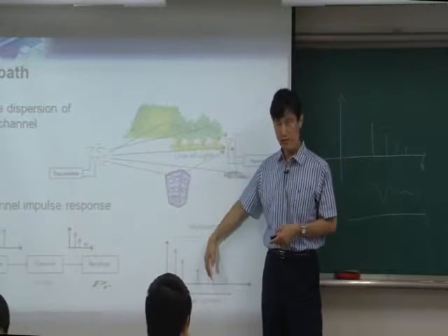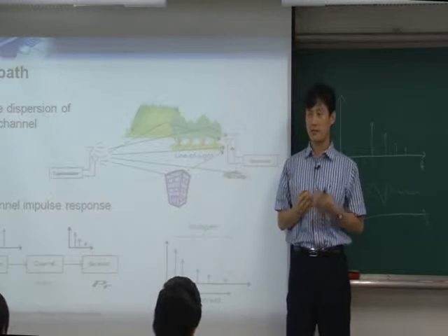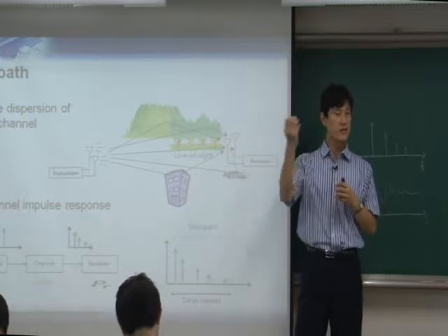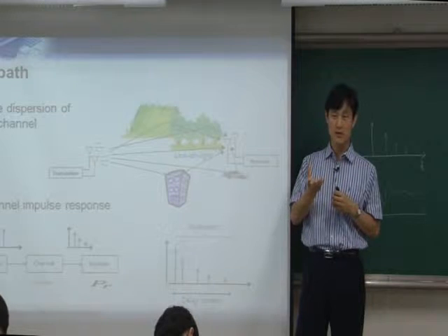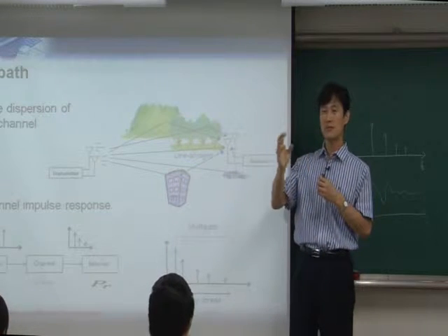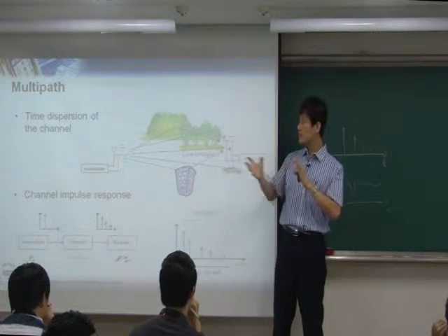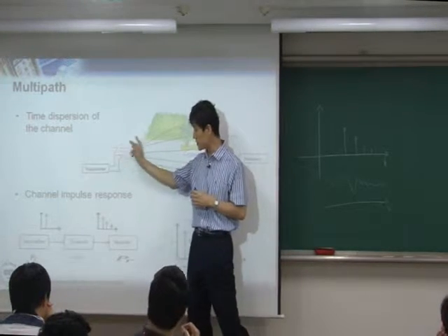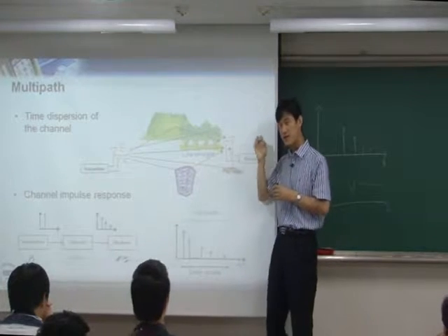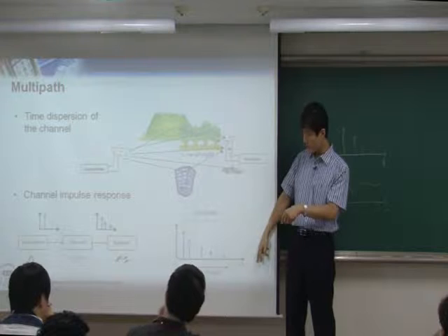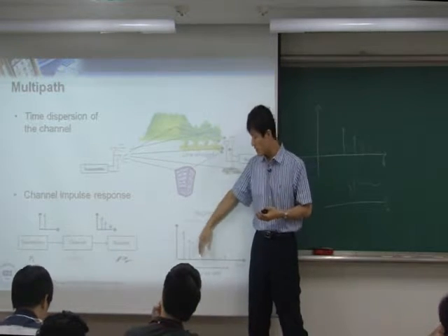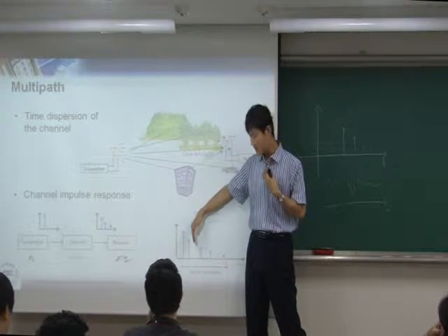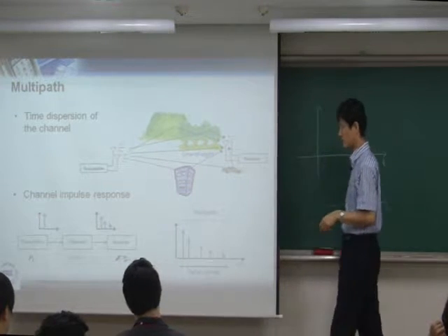You think about that you go on the top of the mountain, okay? And you just shout in the open air, then you'll hear a reflection of your voice, which is an echo, right? But you are not only hearing it just once, you're hearing it multiple times due to the reflections, right? That's exactly what's happening here. You transmit something, but you keep receiving multiple copies, each one with a different delay. That is the power delay profile. This power delay profile basically shows you what the delay of each different echo would be, and how many significant echoes you might have. Okay, that's the power delay profile.